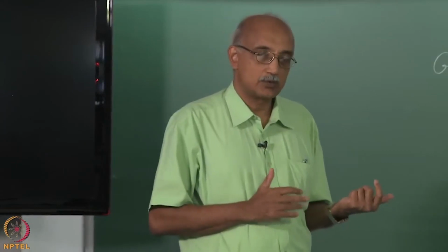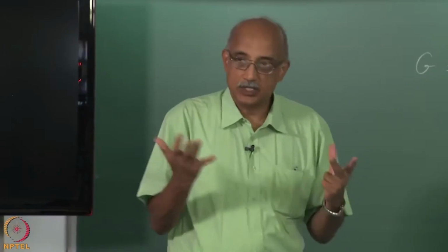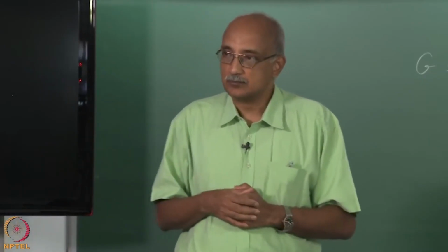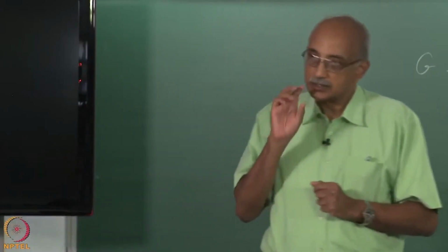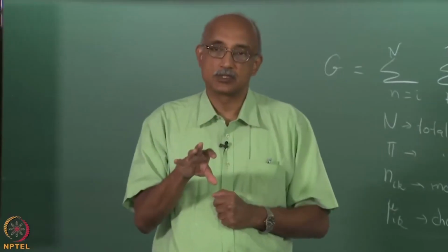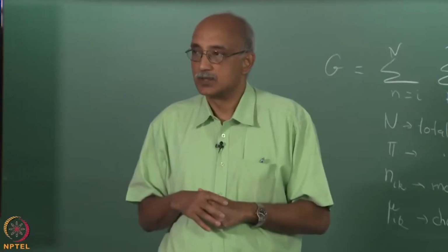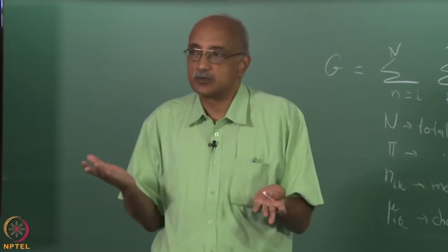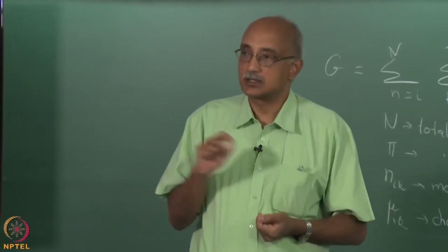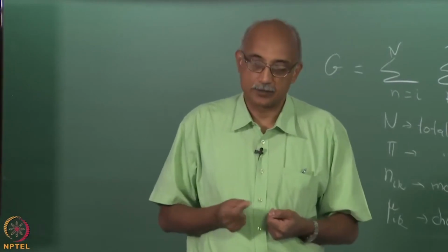This approach is what I would call more of an engineering approach, where you do not just treat the CVD reactor as a black box and do this entirely mathematically. If you know that certain species are likely to form, you can actually force the program to treat those as more likely to form than other species. So, that way essentially the convergence will be faster. So, you can use a few tricks like that depending on your insight into the system to get your results in a more efficient manner.